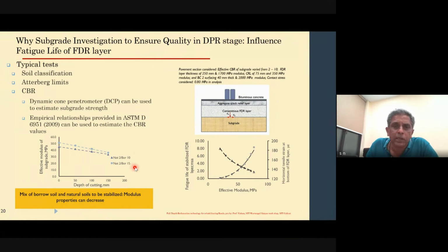Now, the additive requirement, the chemical additive that you are adding along with cement, is set at 3% of the cement content. Now you have an area-wise distribution of cement, which is 20.1 multiplied by 3%, which gives me the dry powder spread of 0.6 kilograms per square meter that I'm working on.